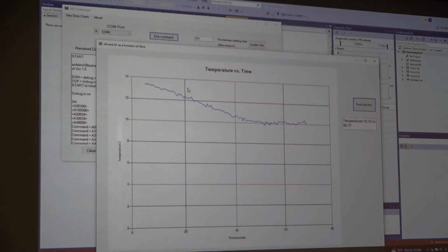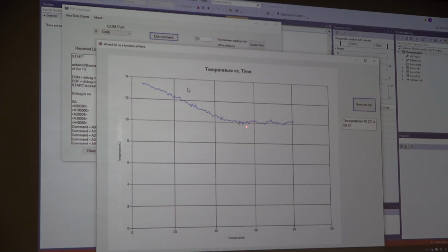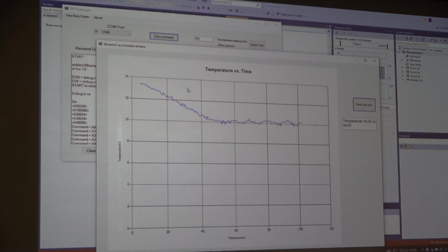Okay. Not as dynamic as I would have liked, but you can see that it is in fact crashing below set point right there, it's below set point there, it's below set point. It doesn't have to be below set point long before the thing just puts on a whole bunch of power. So we're oscillating about set point because I've got too much I. So you want to be very careful with I.